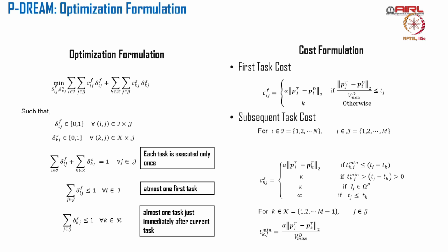If both of them are going to the same task, we have to resolve who has the minimum cost, and he will take that particular task, which means the other has to re-optimize his problem leaving that particular task, right. That needs to be shared, and consensus needs to be created so that they know their decision. All these should happen very fast, and should be computationally light also. So, they will solve this particular problem to resolve. Once some task is infeasible, they will just assign a large value so that they do not get that particular task, right.